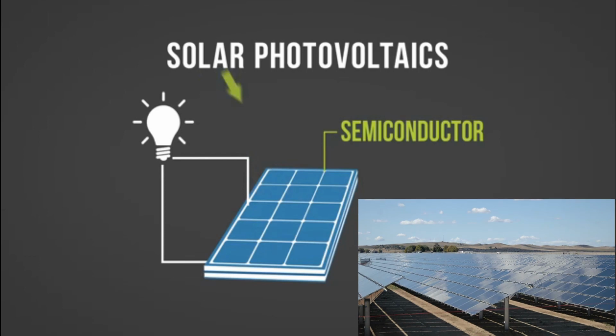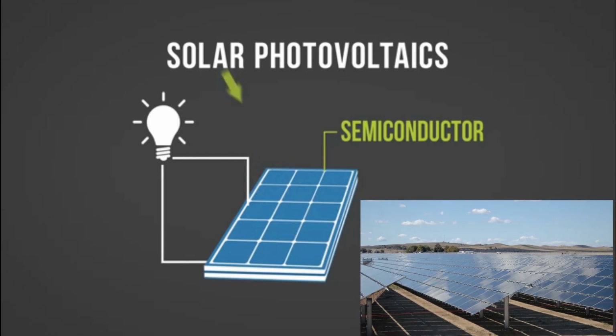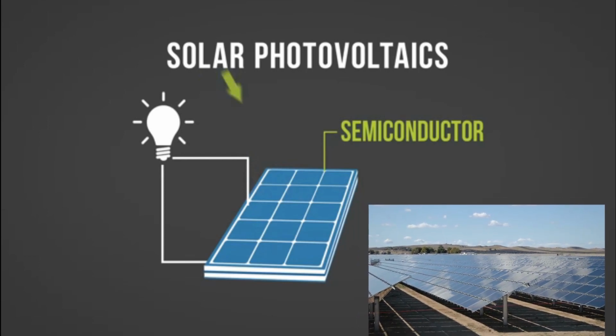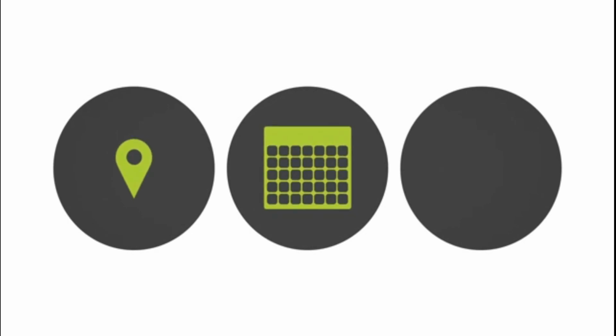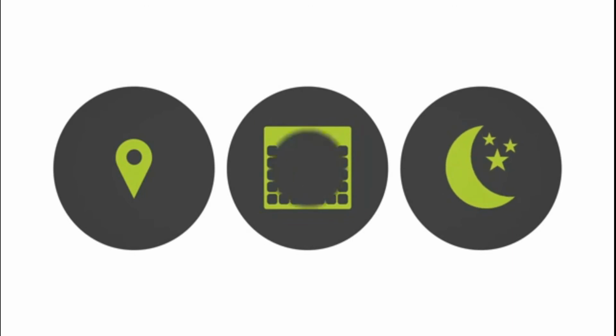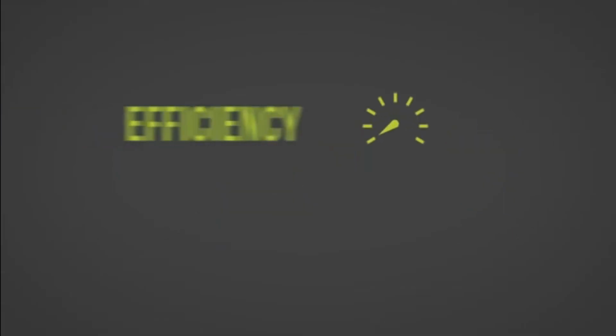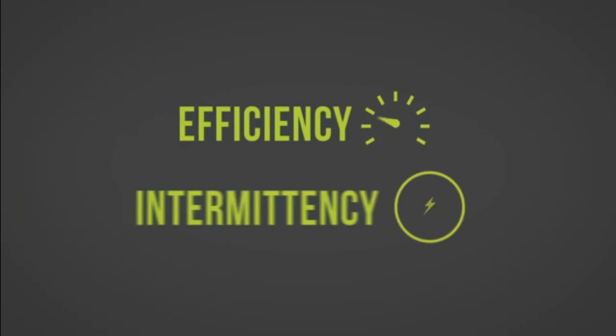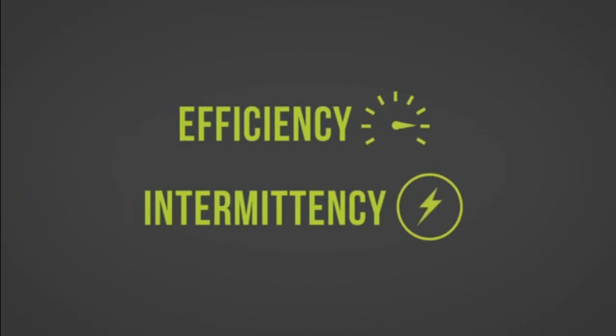The advantages of solar PV are low cost production and easy to maintain. The disadvantages are high capital cost per kilowatt hour, large area required, usually remote from load centers, low capacity factor, operates only during the day hours, large output losses, generates no reactive power, and sometimes wind issues even.